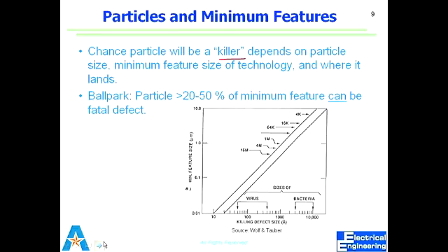So with the technology being pushed, having many more devices, much more dense device design, we are increasing the number of devices from 4K to 16 megabyte and all the way down. Our feature sizes are going down, and so is our killing defect size. Right? So we have to make sure particles above this size are filtered.